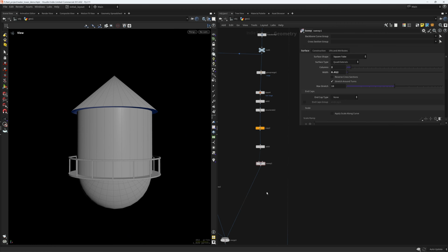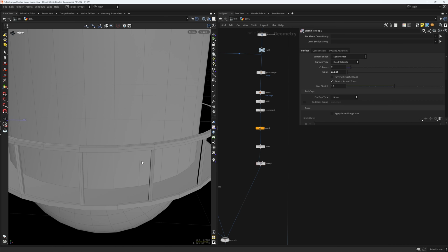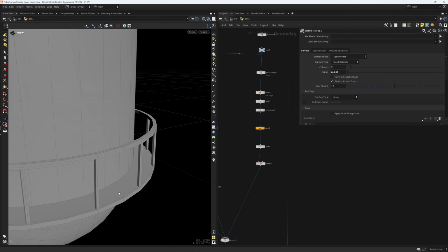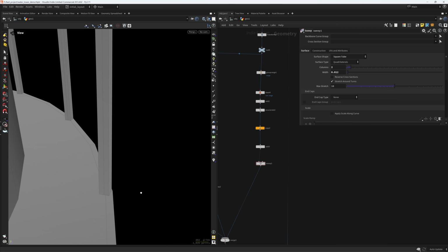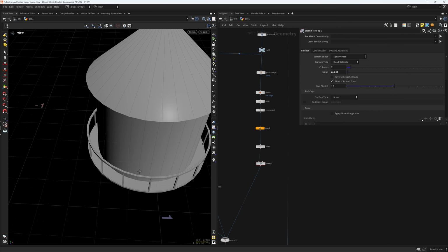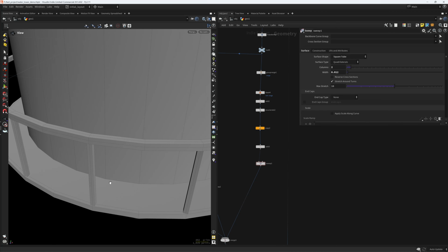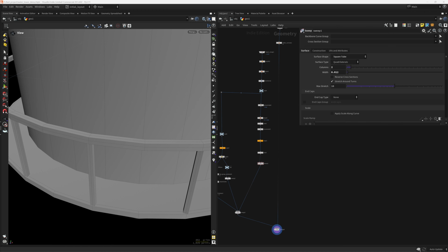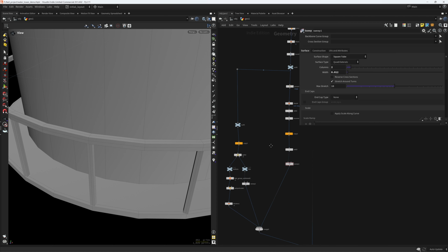Let's move on. So before we move on, there's still some things I want to do in this platform to create in here a cross geometry along these divisions. And also, as you can see, this is not oriented properly, so around the circle. And we need to create some normals or an up attribute pointing outwards. So this will involve just a little expression, and we can actually take advantage of a preset.